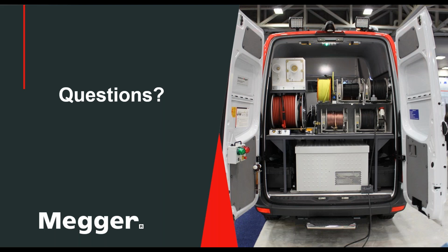Now, there are some tests you can do when you don't use high voltage, when you just use low voltage signals. For instance, if you just use a TDR, you can have a motor connected, but the motor must be de-energized, obviously, right? So that way you can see, because the motor windings will show you on a TDR an open circuit, okay? So it is possible, but the basic rule is any high voltage testing or fault locating, you must be disconnected on both sides of the circuit, and on the near end, you typically connect your equipment.